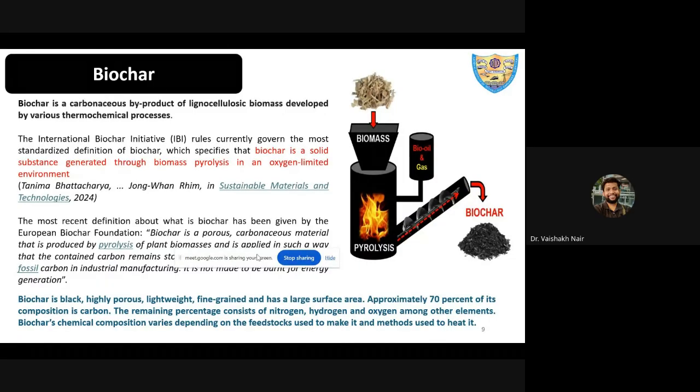Now, this is again the first point I have already stated in the previous slide. The method also we stated in other, and same way also in a particular technique, thermochemical method, let's say pyrolysis itself, based on the temperature and the time you are basically heating, the residence time, you will see the biochar produced at 300 degrees Celsius for 2 hours will have a different property when compared to biochar synthesized at the same temperature after 4 hours.